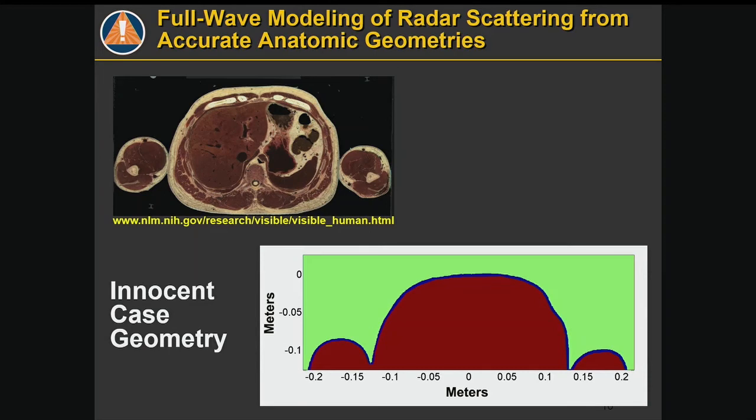And interestingly enough, if you're modeling this at 60 gigahertz millimeter waves, wavelength being of the order of 0.5 centimeter, well, a millimeter of skin, especially lossy skin, is enough to make the response from anything on the other side of the skin pretty much insignificant.